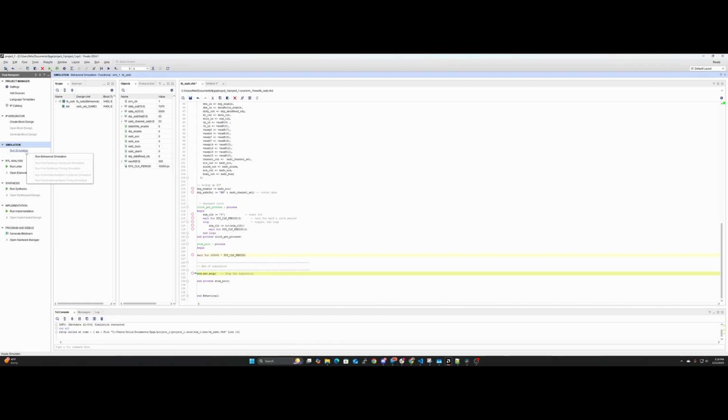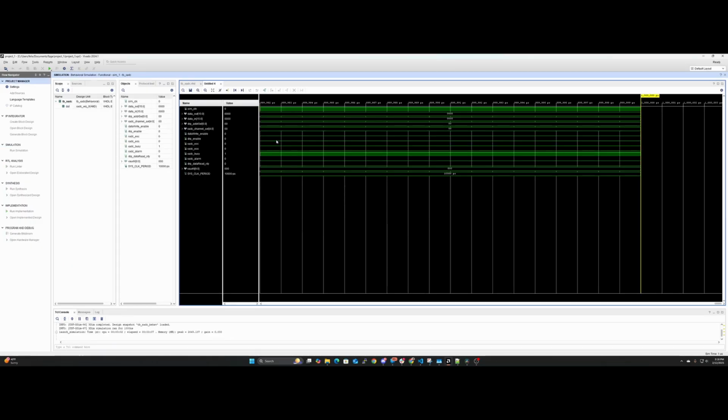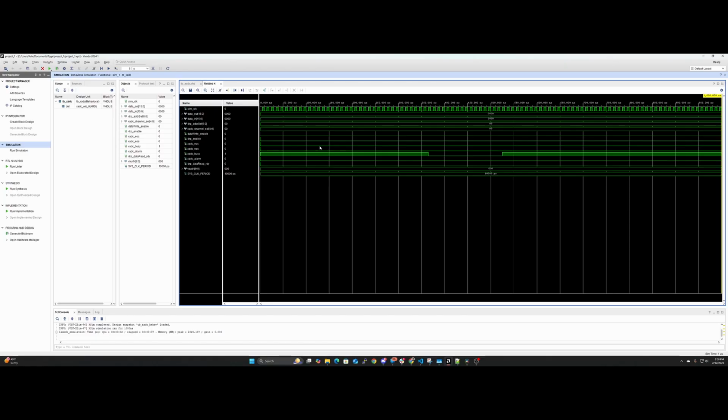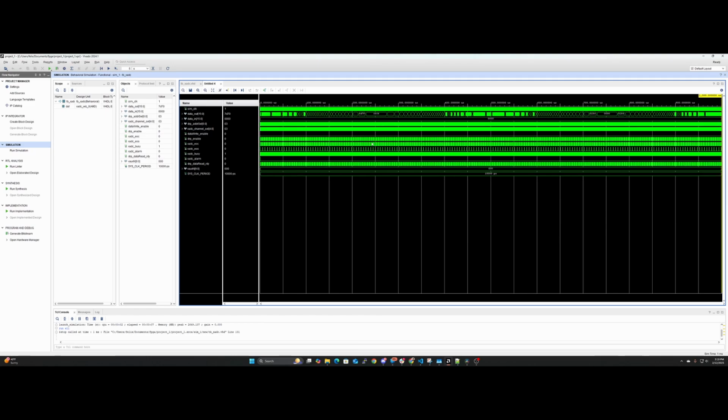We're on our simulation. Press OK. Expand it, and we see it's only gone to 1,000 nanoseconds. Yeah, 1,000 nanoseconds. We want to step it out, so I put mine to 5 seconds. Hit play. Go back, expand it, and you'll see this.